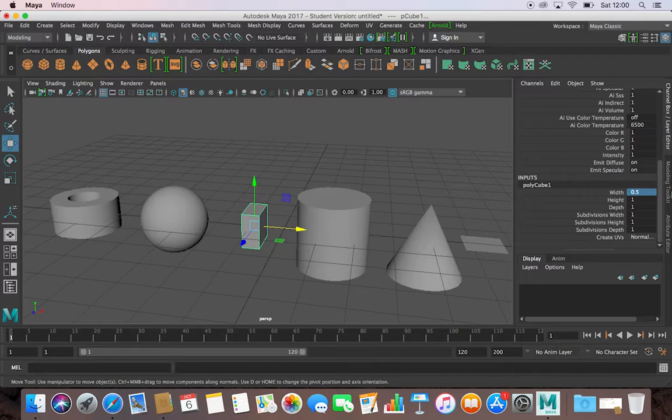And so if you need them to be different shapes, then working on the inputs helps because you can change the input size before changing the scaling, and then anything that requires processing of multiple objects scaling will all work uniformly without it being all wonky. So put that back to 1. We won't look at height and depth, it's the exact same.